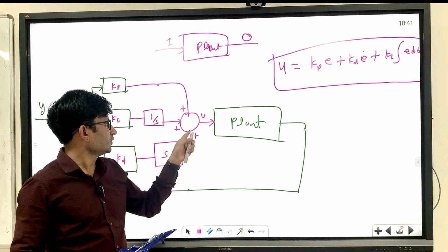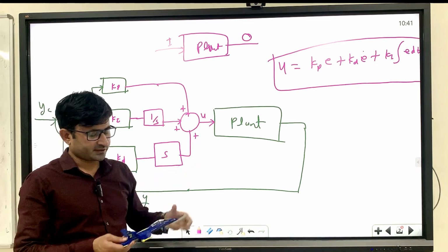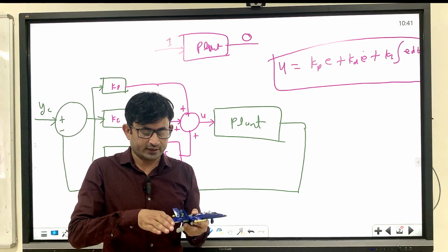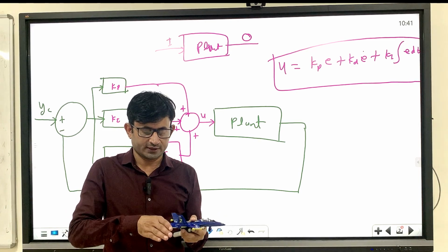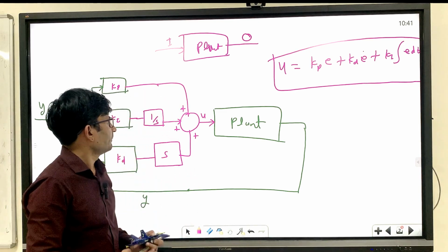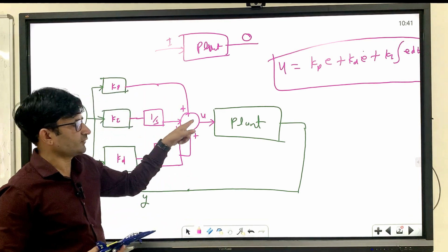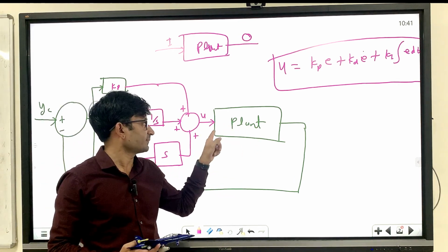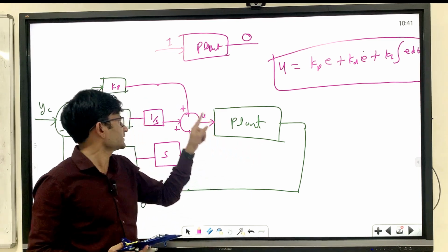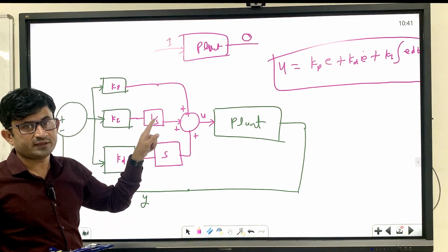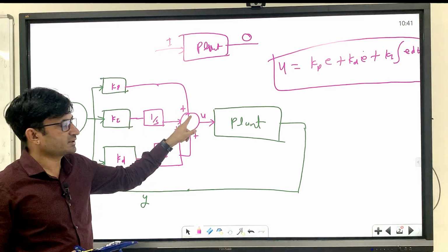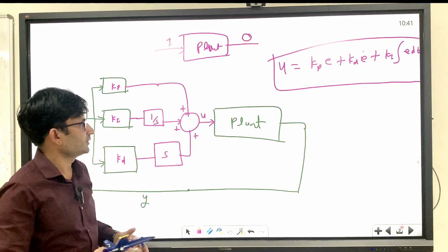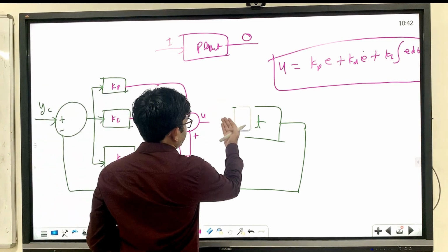For example, in the aircraft case, let's say you are deflecting the elevator, you can deflect the elevator plus 10 degree up and minus 15 degree down. But if in computation you are getting 20 degree or let's say 50 degree, you cannot supply this directly to the plant, because this is a math block. So you have to be very careful, you have to check what the computation is going on here before supplying to the plant. So in reality, put the physical constraint here.